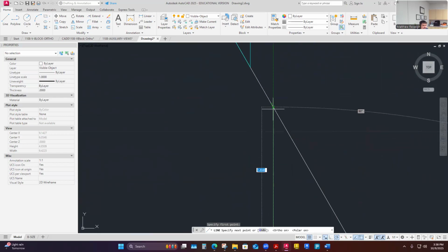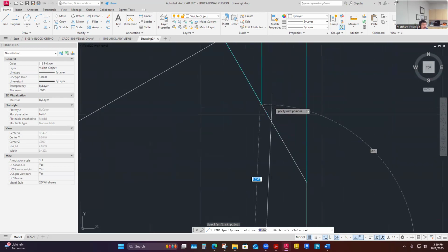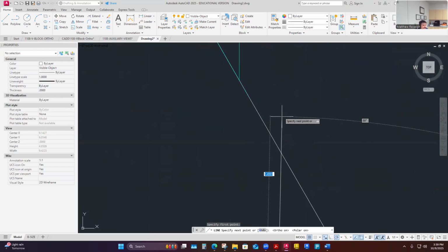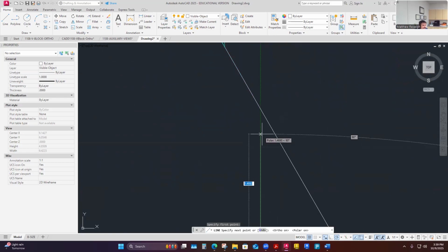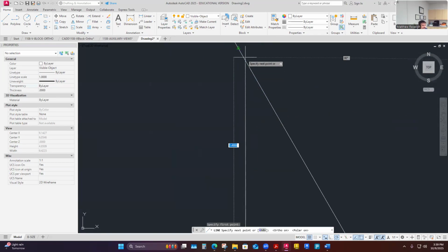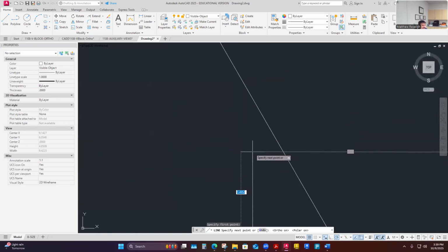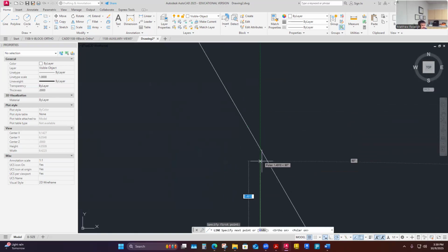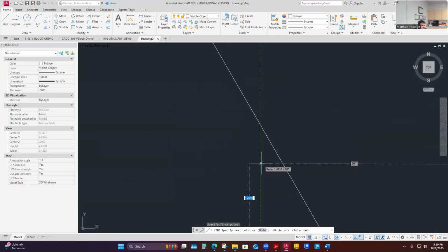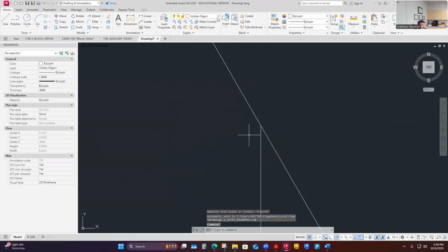So there maybe is a really, see, I could have just grabbed a different grip that I didn't know. If I'm backed out here, I thought I had it. So let me just really zoom in here, make sure this is straight up and down. Make sure I'm looking for an intersection point. I'm not looking for any other grip on here. I'm just looking for this intersection. So I can zoom way in. I'm looking for my straight up and down 0, or I could type that in, but that's where I want to be. And this is the intersection. Okay, cool. Now from there, I'm going to see if I am a little more accurate when I project up here.